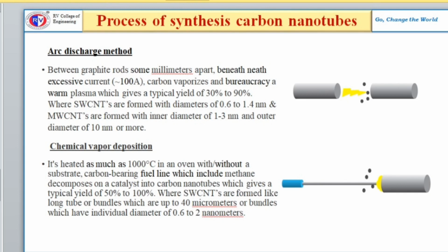For the next we will be taking chemical vapor deposition. The chemical vapor deposition method is to cleave a carbon atom containing gas continuously flowing through the catalyst nanoparticle to generate carbon atoms, and they generate carbon nanotubes on the surface of the catalyst or the substrate.